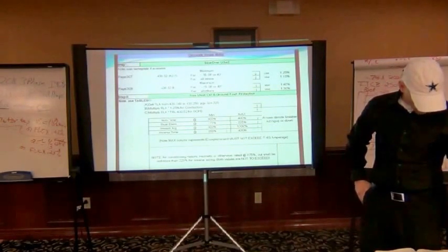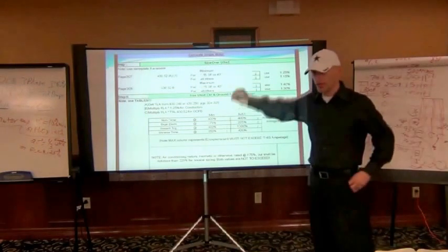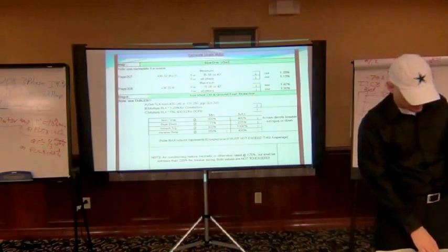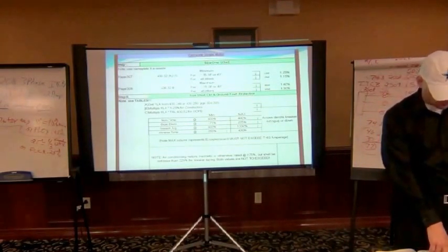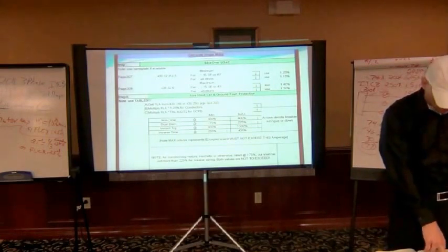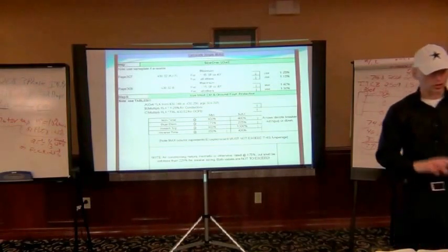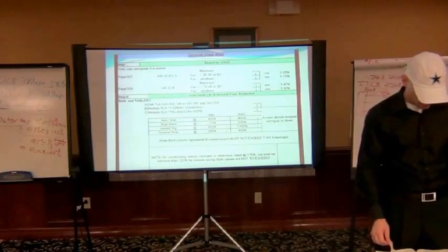If you look at 430.28 on page 318, what I just said is that when you look at that top part where it's usually a short run, that's your rule here. That's the 10 foot, 10% rule. That's on page 318 under 430.28(1). And then at least 1/3 that of the feeder under note 2, and then also having a capacity not less than the feeder conductor. So it could be one of the three. If you wanted to, you could just run a full-size tap, not worry about it.